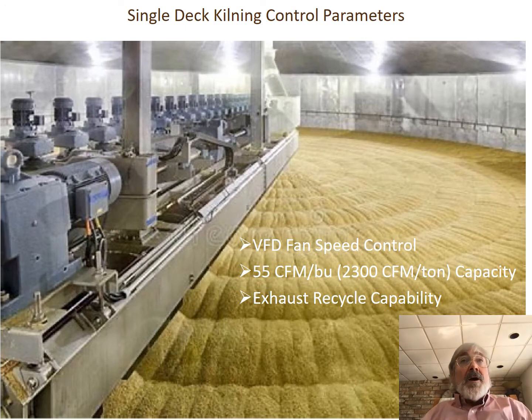You can go higher than that, but be aware that when you do, you're probably going to run into issues with channeling, which is where one part of the bed will dry out and all the air will run through that part without drying the other parts.